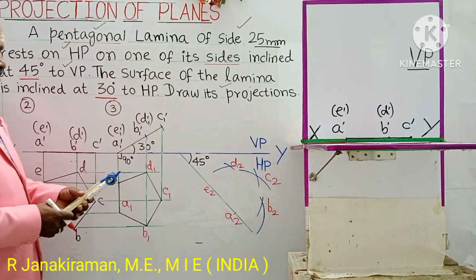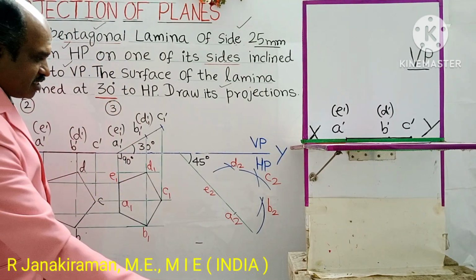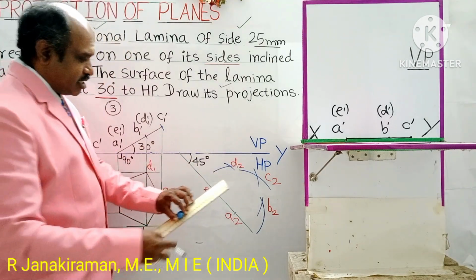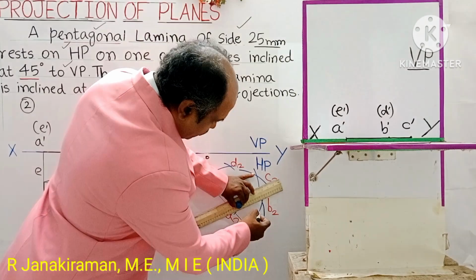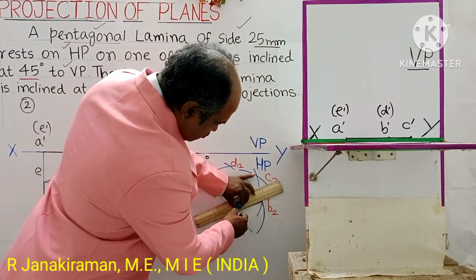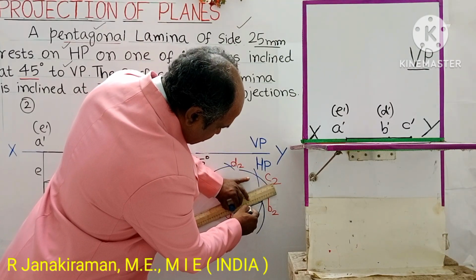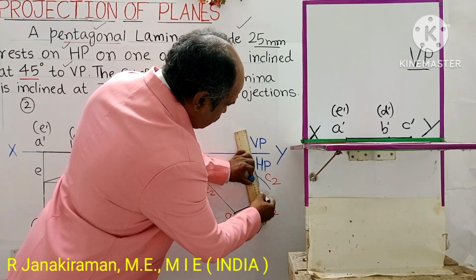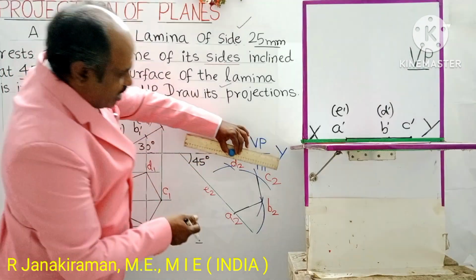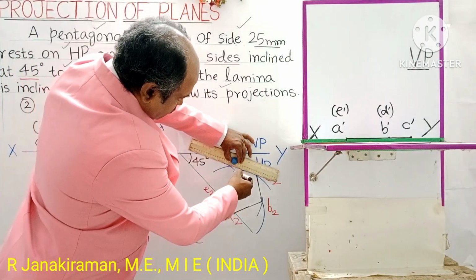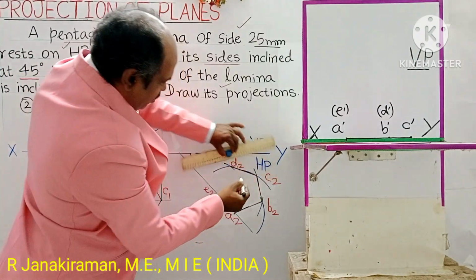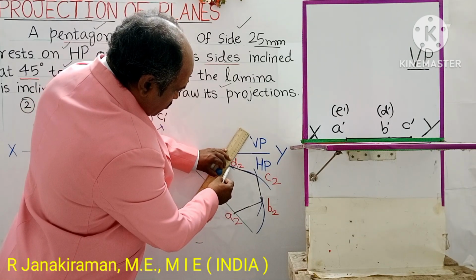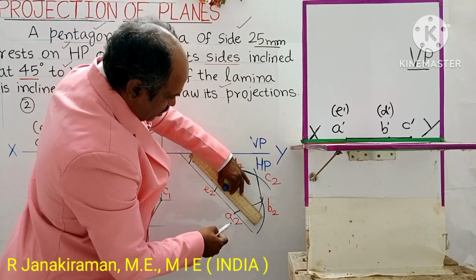Join all those points by freehand scale, starting from A, with an HB or H pencil so that it appears dark. Join A to B2, B2 with C2, C2 with D2, D2 with E2, and E2 with A2.